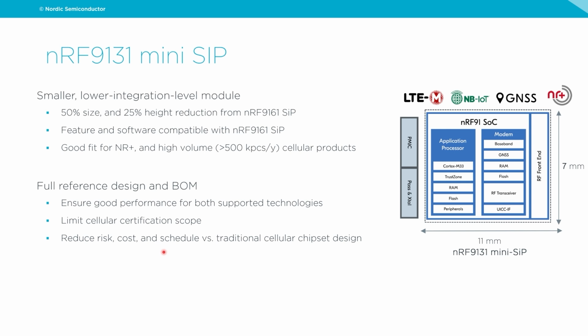The reason is that because it's not pre-certified, the customer has to do the certification. That is something that typically only pays off if you have really high volumes, where you can dilute that certification cost over a large volume of devices. But you're not alone in this journey, because Nordic provides a full reference design and a bill of materials that you can use for your certification process.